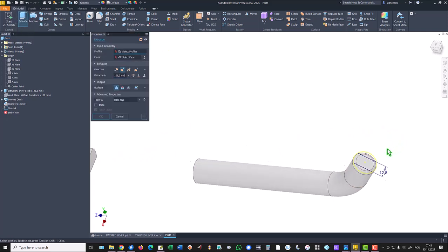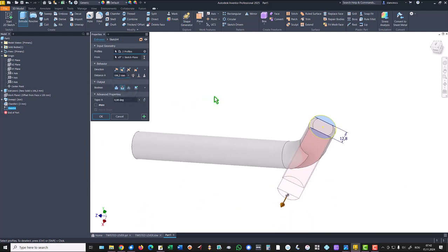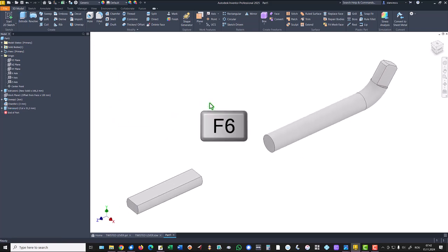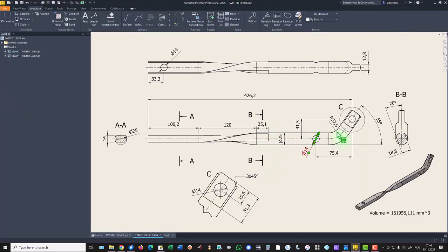Okay, finish sketch, extrude, and we select the two sectors with cut on 31.3. Okay, very nice. A similar cut we must apply to this face. You see, this is 18.8 at 20 degrees with a depth or length of 27.1.